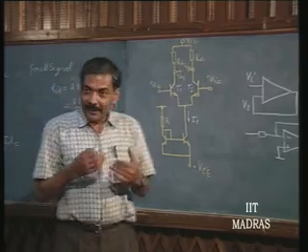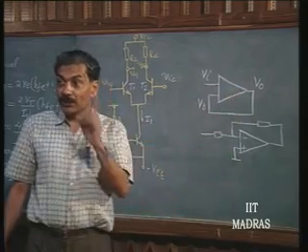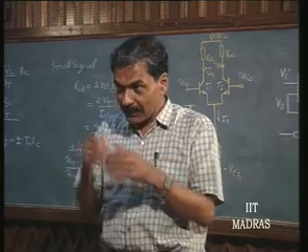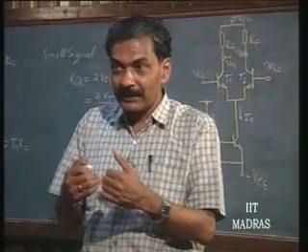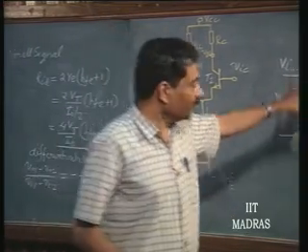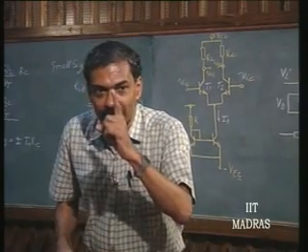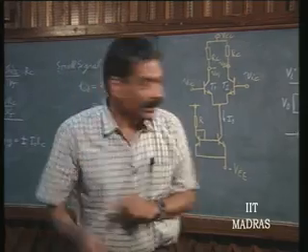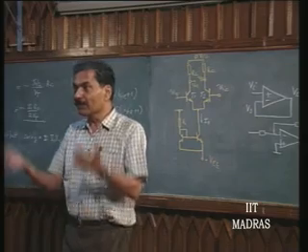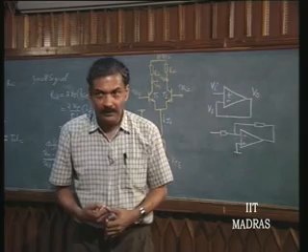If you want any op amp to be used as a buffer stage, then make sure that there is no common mode problem. And the fact I mentioned: if the input stage is designed such that it is likely to go to saturation and you are going to use it in this configuration, then the problem of latch up is going to arise. Is this understood? That is where this so called negative feedback itself turns into positive feedback because of the signal, and thereafter it refuses to come out of the positive feedback situation.